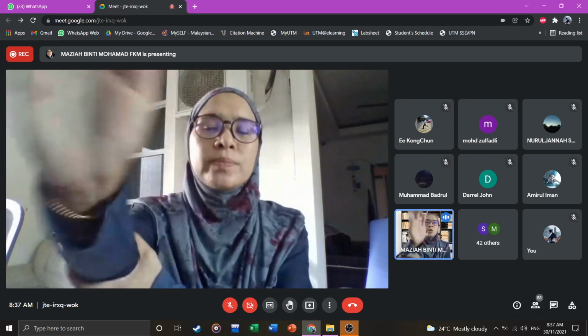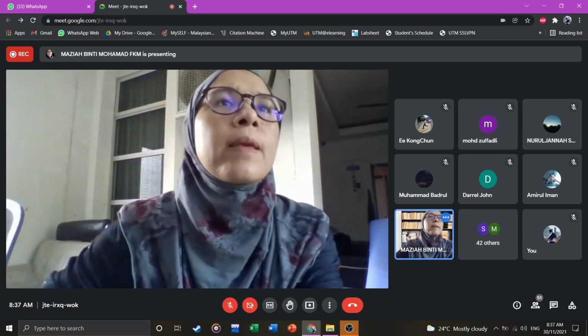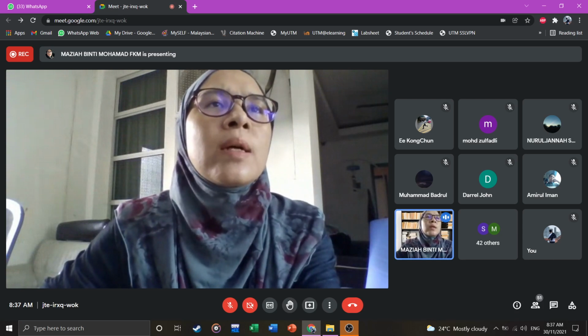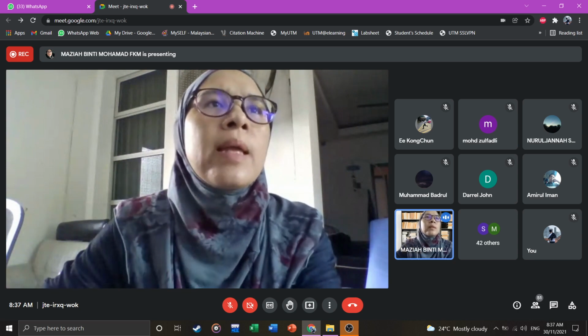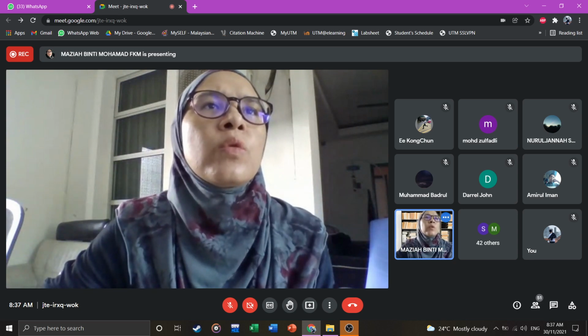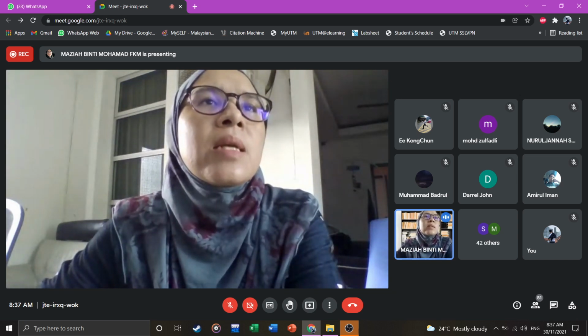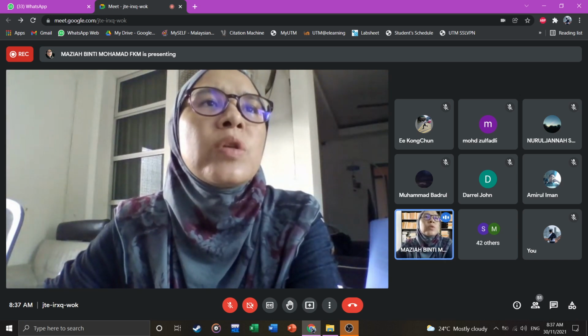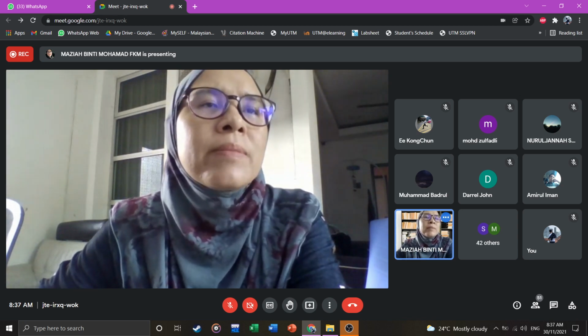All right. So in order to start drawing a block diagram, first you need to have the library. On the toolbar here, there is a library browser. So you need to click this library browser, and it will open a library.